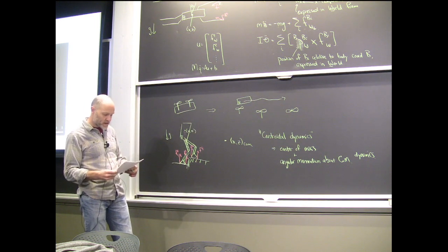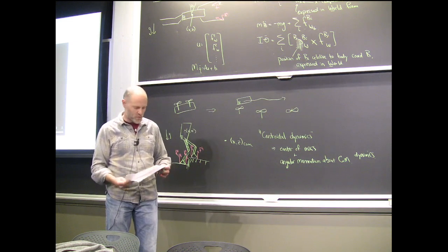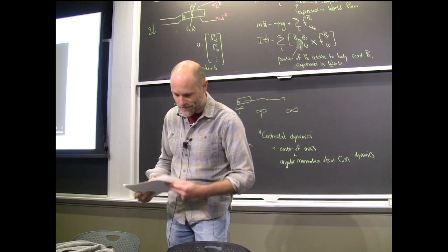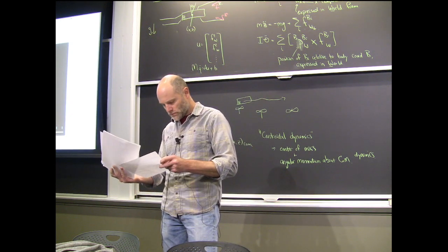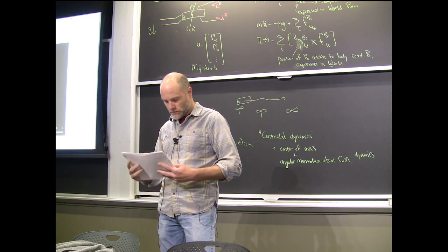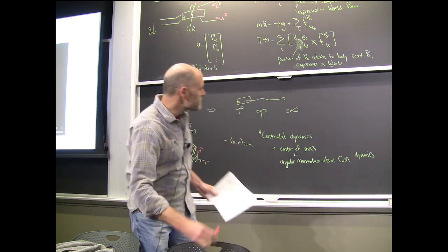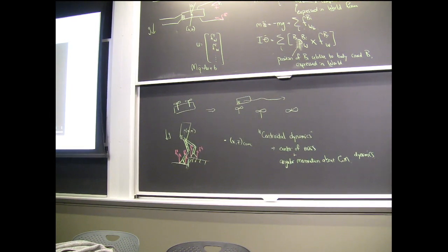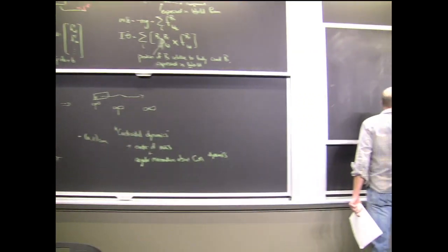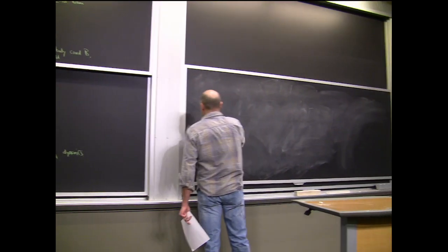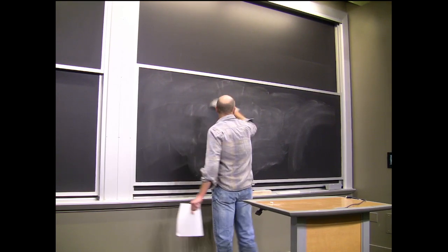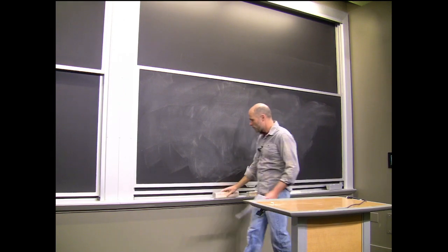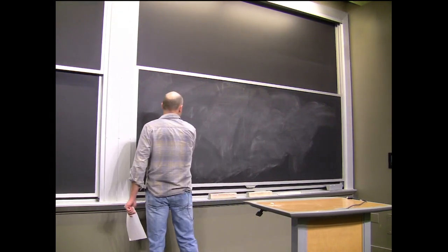Okay, so let's think about exactly what's happening in the equation and maybe what the zero moment point is and why that takes the forces and makes them a nice summary of the forces. The ZMP is particularly potent in the case of flat ground. It actually does extend pretty nicely. But let's just think about the dynamics of my center of mass, basically those equations right there, in the special case where all of my forces are coming from the same ground, okay?